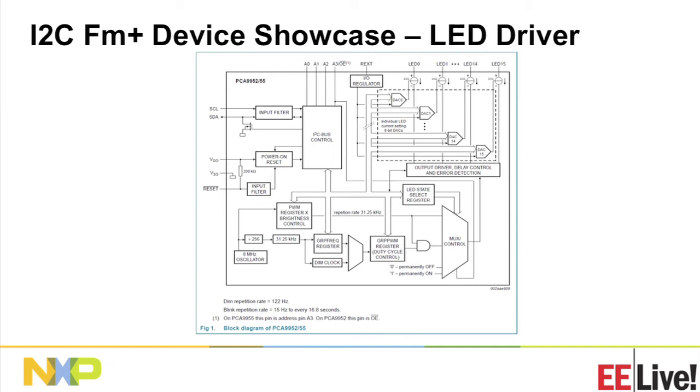Here's the challenge. To make the first LED light up, you need to send it 55 bytes of configuration data. So there's a challenge, someone sent 54 bytes and wondered what happened. Yeah, it's a challenge to get this to light up because there are so many programmable variables inside the chip, you have to have the full suite before anything will happen.